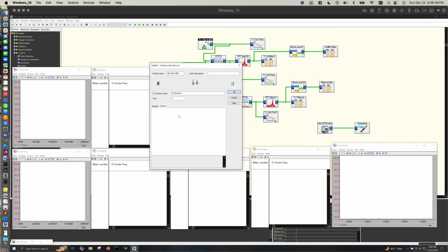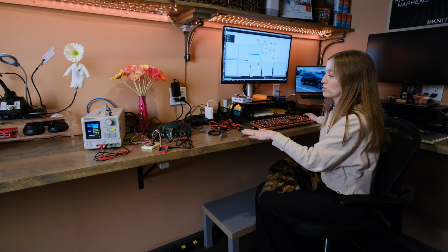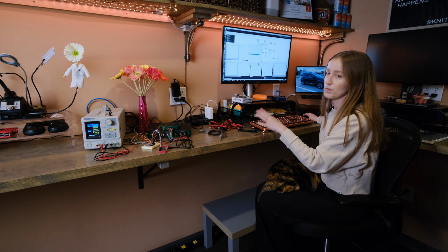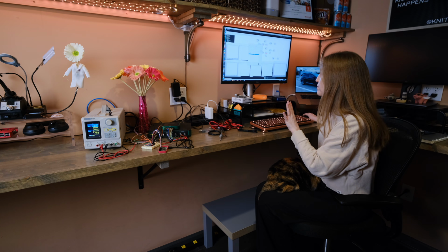I'm not sure what this area is. This seems like this is blank. It's another beta quirk, but I think you'll notice that here, I think this is another quirk of it being a beta driver. The block will let you have 2 different input range settings. That's actually not possible on the Analog Discovery 3. Both channels, I believe, need to be the same input range at one time.